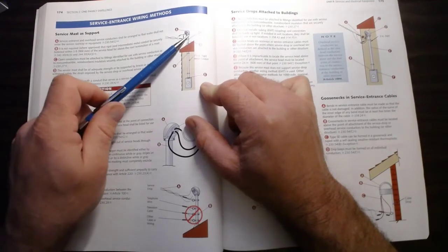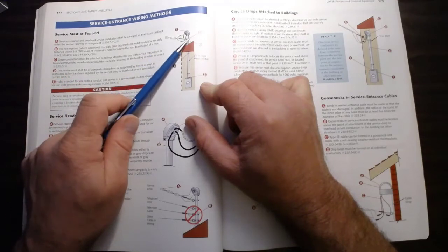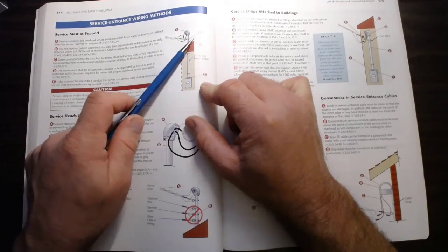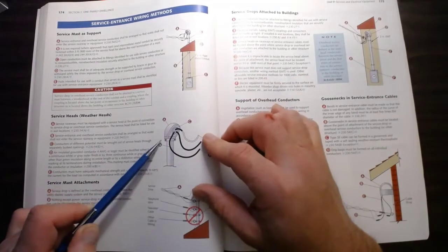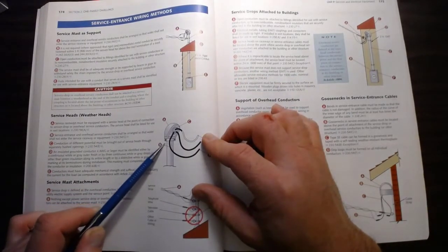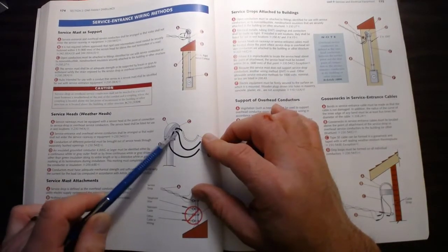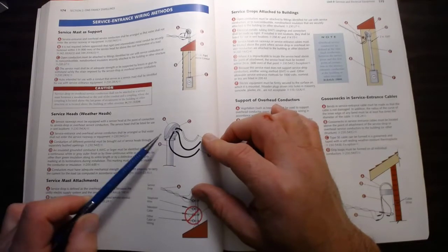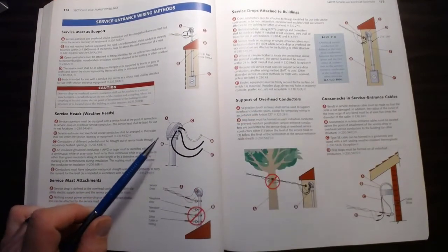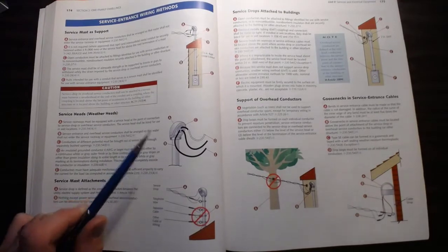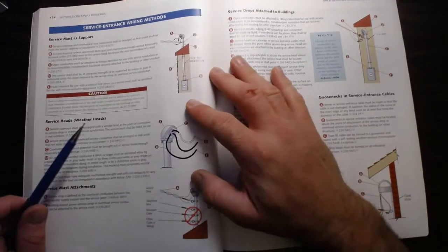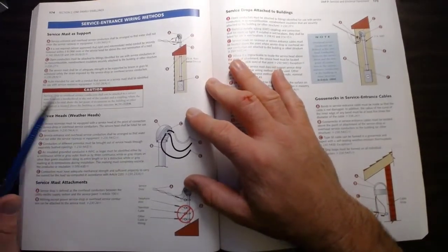And then you're going to cut this end to be the height that you need and just cut it off. And then this weatherhead will then clamp on to that cut piece of pipe. Make sure, of course, it's reamed, but you don't need to thread the top of it, which is very helpful when we're trying to install in the field, especially residential construction.